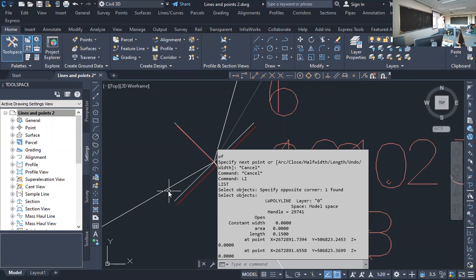Okay. Let's start talking about creating a drawing. Because everything we've done is just, right, in this space in CAD. So there's 2 spaces in CAD, 2 working spaces. They're called model space and paper space. Model and layout. Model is the real world.